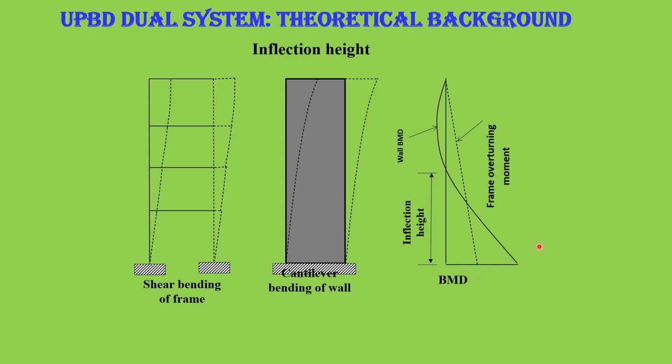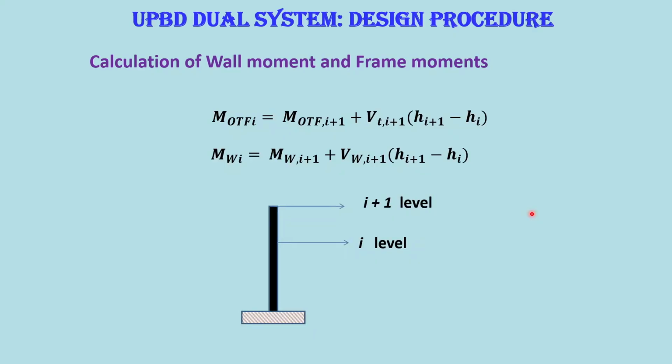These are not final values. Similarly, wall bending moment also shall be done like this, distributing say unit load over different floor levels and finding the bending values in the wall. That will be good for the design purpose. Now, how the moment etc. are calculated for the wall, this we have discussed earlier also in connection with the DDBD method for dual system.